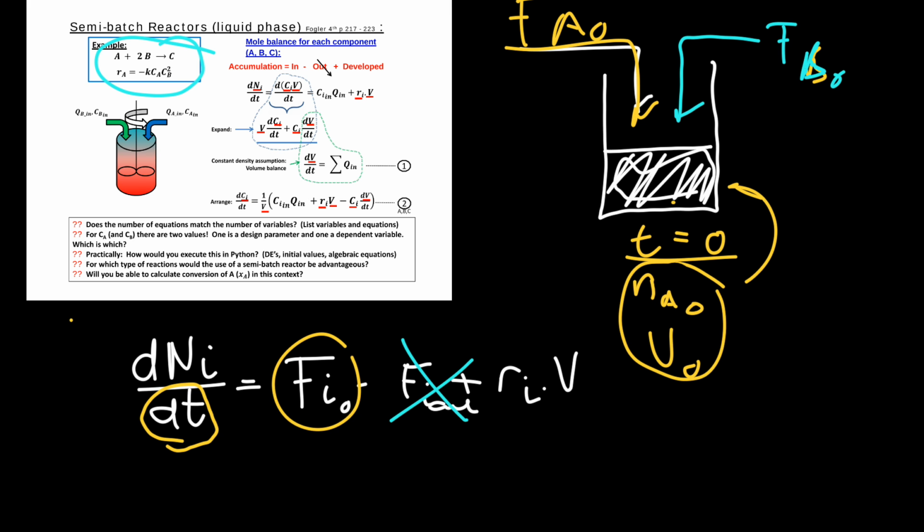in the example that we are going to consider in this case. It is easy to get confused with all the different concentrations that are in play when we do this kind of analysis. So what we need, we have an inlet concentration. So maybe, rather write that as CA_in, and we've got a volumetric flow rate v_in. So of course their product will give me the molar flow rate of component A in.